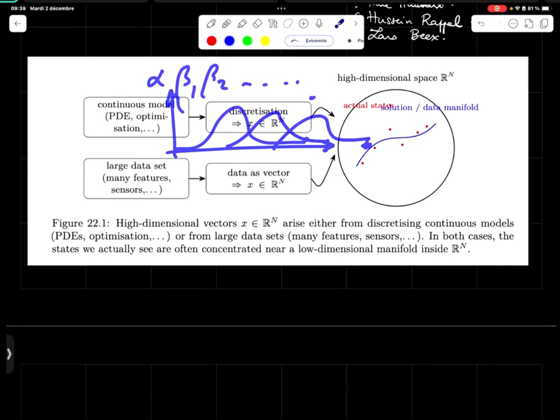And this is what I was telling you last time about Paris law, that you do simulations, you do tests in the lab, you break some concrete, you break some steel, you cycle a piece of aluminum using any sort of loading machine under fatigue, and you look at the cracks and you look at the microstructure, you look at all of that, and at the end of the day you have a law that tells you how much the crack grows if you know the energy that you're putting into the system. So that's something that's empirical, or at least semi-empirical.